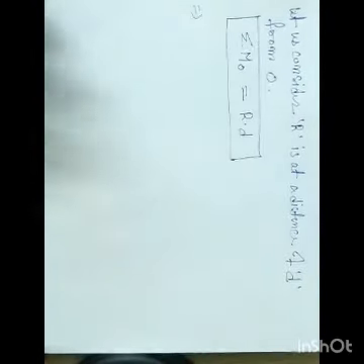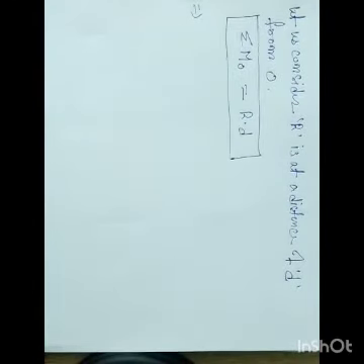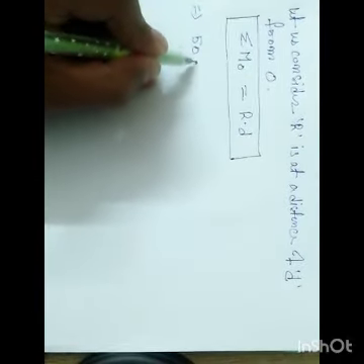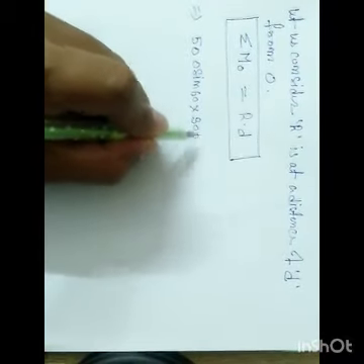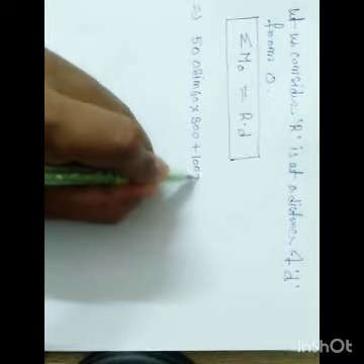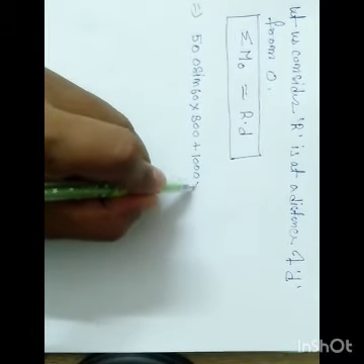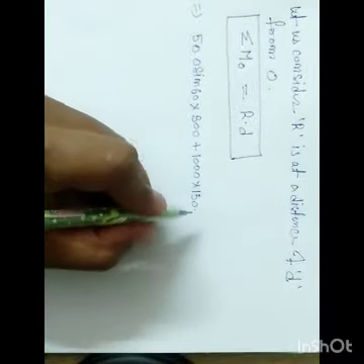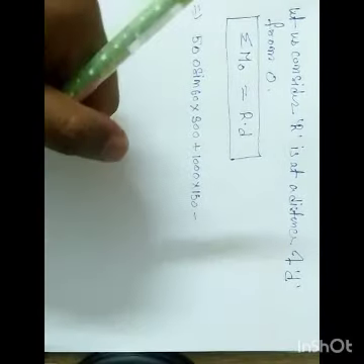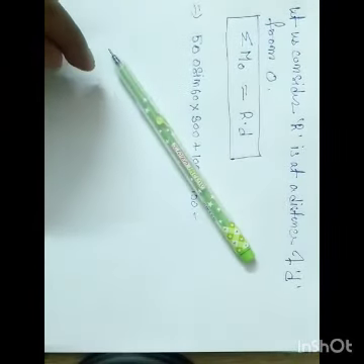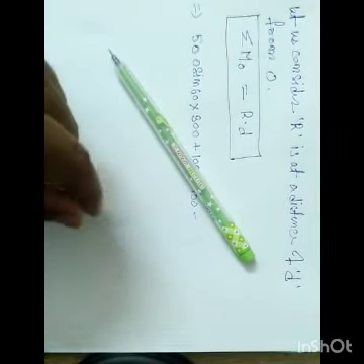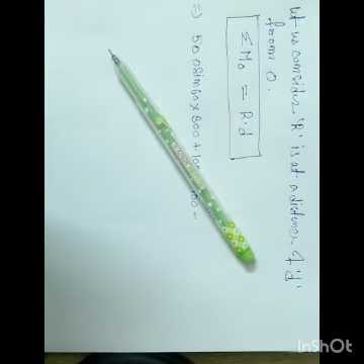Okay, now you can say the moment first, 500 sin 60 into 300 plus 1000 into 150. Simply, the 1200 is vertically downward, you can refer to the figure, minus 1200, and the distance was like this, 150 with an inclination of 60 degrees, so 150 sin 60.